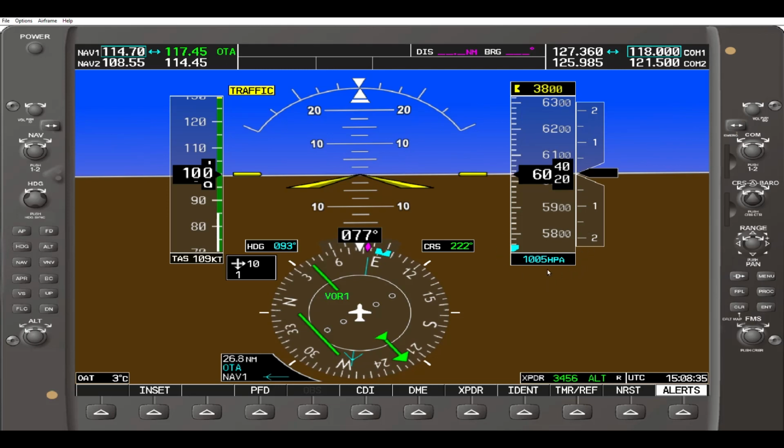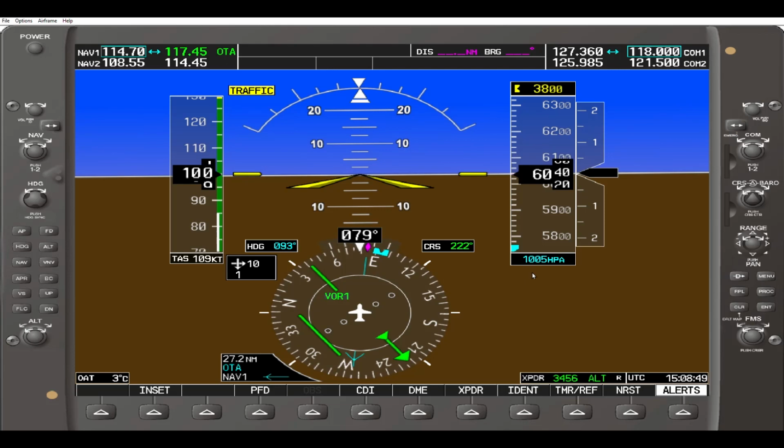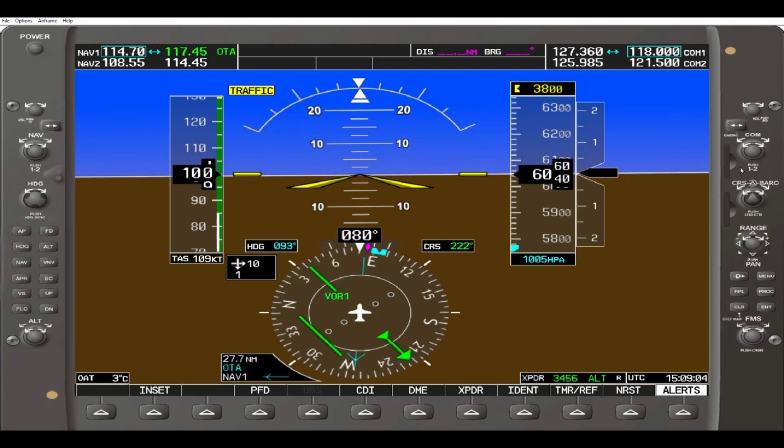Below the altimeter is the altimeter setting. So this is your pressure setting, the QNH that you receive from the radio or from tower, and you set it. To set your QNH, you need to use this knob right here. There is actually two knobs there. The outer one is the bigger one, and the inner one you can see has a triangular shape. It's a smaller one. You can actually see a schematic here.